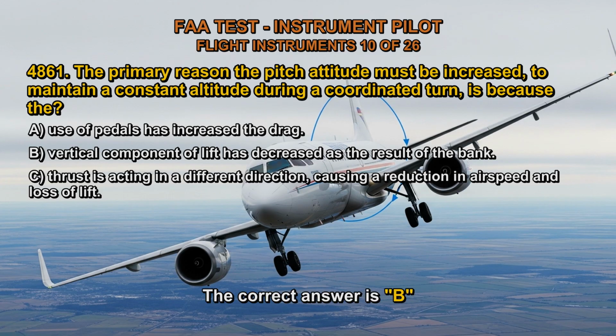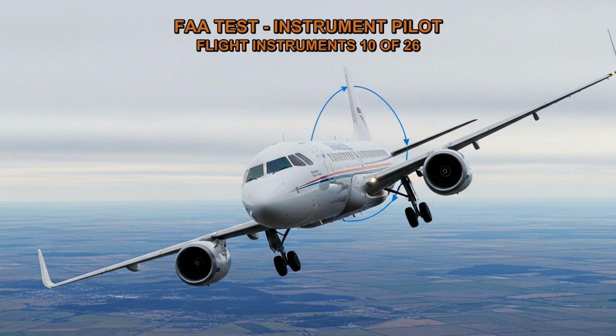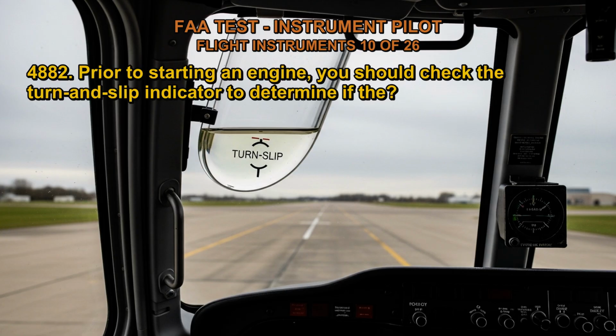The correct answer is B. When an aircraft banks into a turn, the vertical component of lift is decreased as the result of the bank. This is because the lift vector is now angled slightly to the side, which reduces its vertical component. To maintain a constant altitude, the pilot must increase the pitch attitude to increase the vertical component of lift.